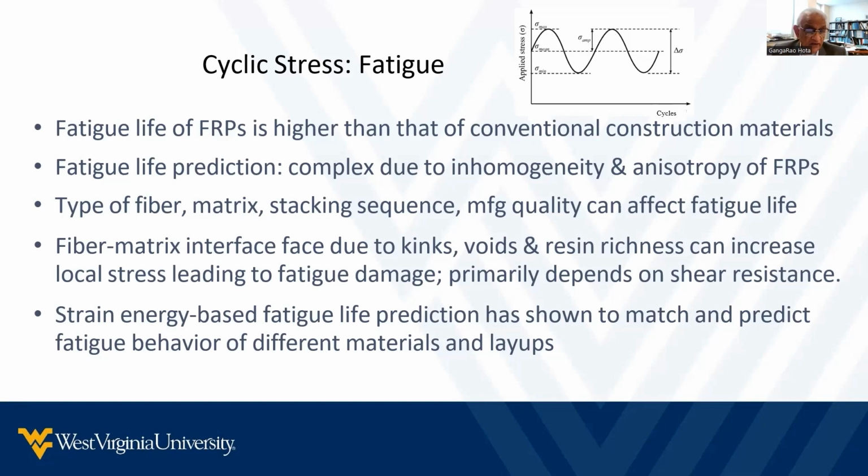That load to failure under fatigue cycles in composites is higher than in metals under the same stress amplitude, which is attributed to better ductility of polymers that transfer forces from one fiber to the other when compared with metals.